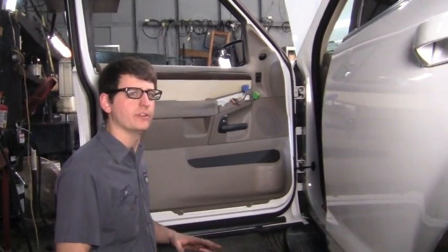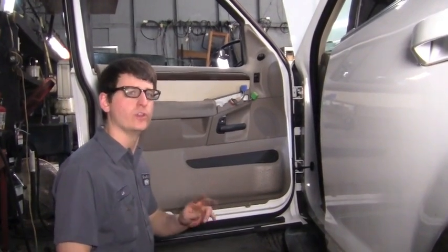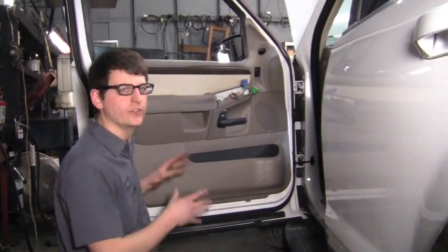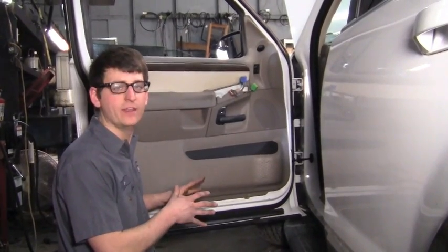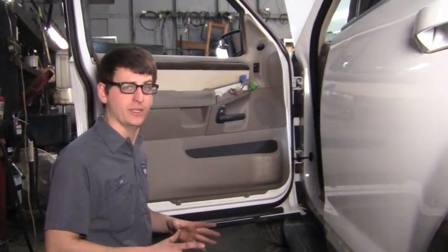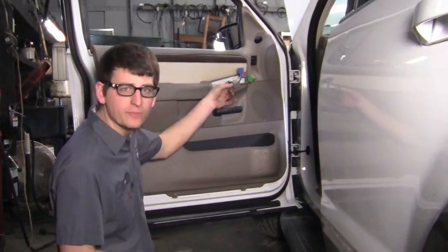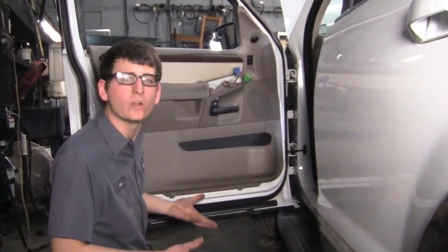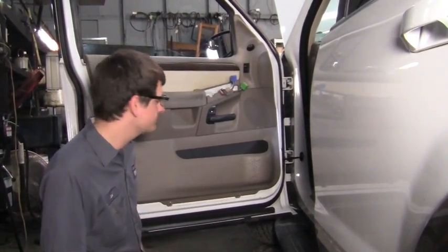Now it's a little bit different than the right rear door. There was 2 screws, and then we lifted up and pulled out. On this door there's 3, so we want to watch out for that. Again, they're going to be 5.5 millimeter, 1 up top here, and then we're going to have 2 at the bottom. We're going to simply pull up and pull out.